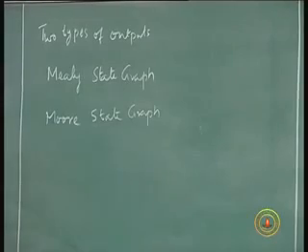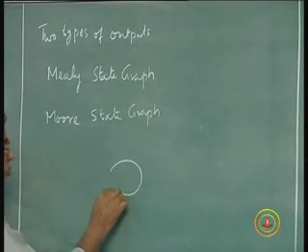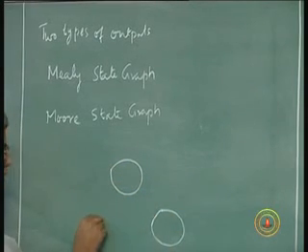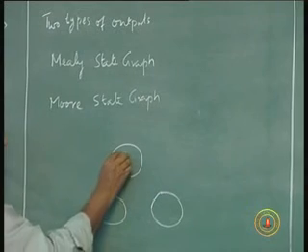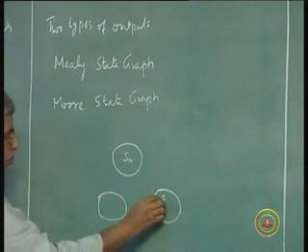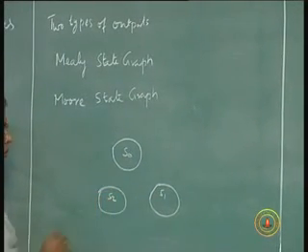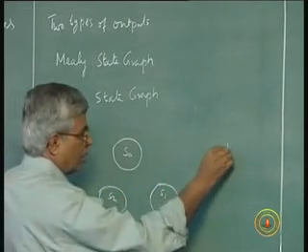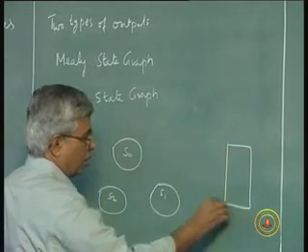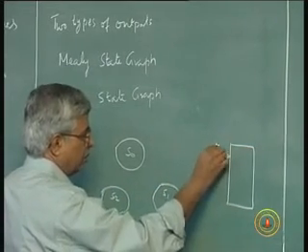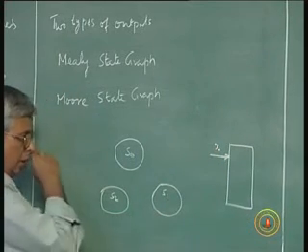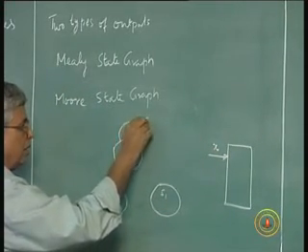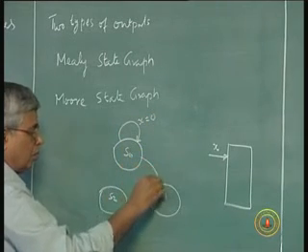What I mean is this: suppose I have a simple machine with three states only. Call them S0, S1, S2. The circuit has one external input, X. If X is 0, the circuit remains in the same state, S0. If X is 1, it goes to S1.